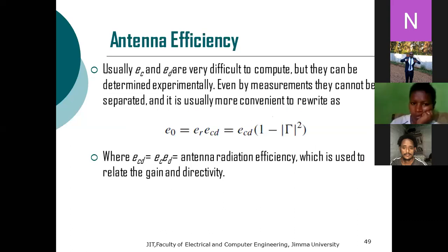Now we have the reflection efficiency. We have here the conduction and dielectric loss efficiency. Then we can rewrite the reflection efficiency in terms of the voltage reflection coefficient, and we can have an expression for antenna efficiency in terms of the conduction dielectric efficiency and the voltage reflection coefficient.